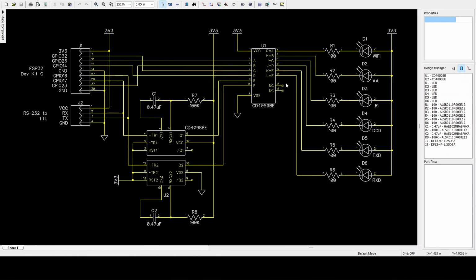This is the schematic for my 8080 Wi-Fi modem. On the left are the pins from the ESP32 DevC module and the pins for the RS232 TTL module. To keep space to a minimum, I decided not to install a header socket for the ESP module. Instead, I inserted the module directly on the proto board and soldered wiring directly to the ESP32 DevC module header